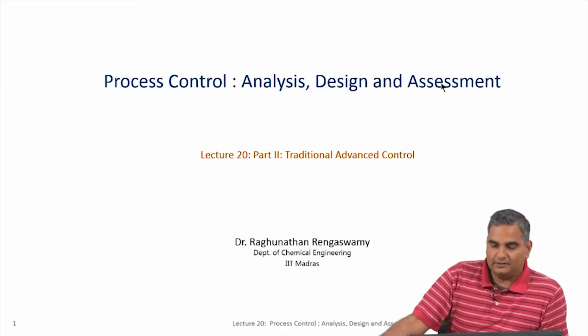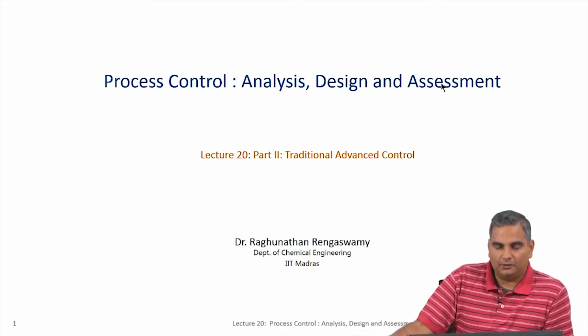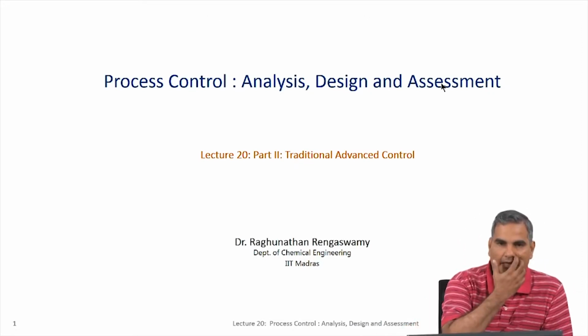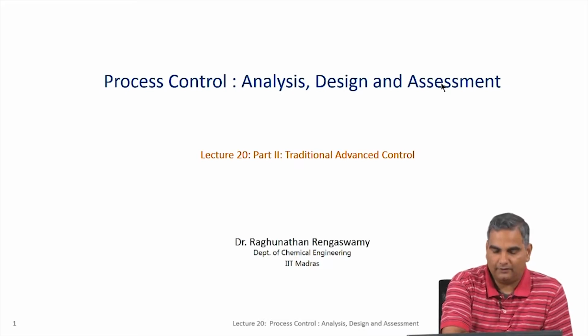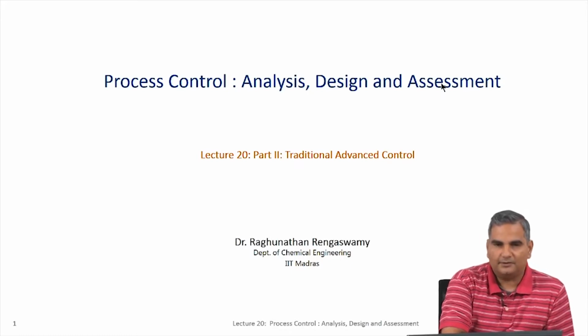We will continue with the lecture on inverse response systems and controlling inverse response systems. In the last class, I explained what inverse response means and how you identify inverse response systems by looking at the transfer function model. Just as a quick recap, inverse response systems are systems where the initial direction of change is different from the final change.